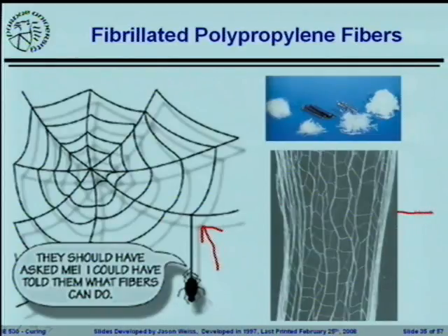When we start talking about fibers, we're really looking at how small the fibers are, how well they're distributed throughout the system. Now, one of the big problems is we want big, coarse fibers to bridge the cracks when they start to form because they're going to provide a lot of stress transfer. But we want a lot of fibers to help with things like stiffening the material while it's in a fresh state or creating places for water to wick to the surface. If you have a lot of fibers with a lot of surface area that go into the mixing process, it can become a real problem and the fibers won't mix in very well.